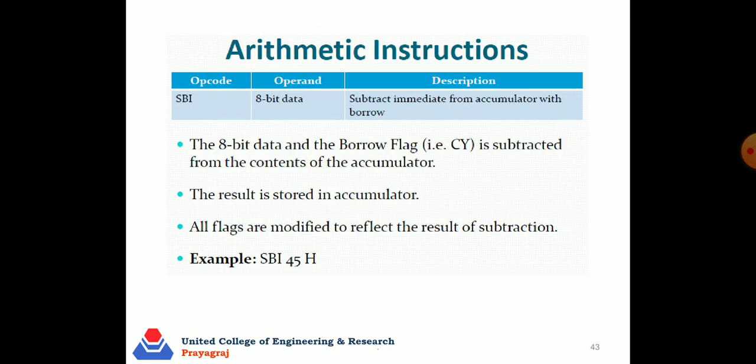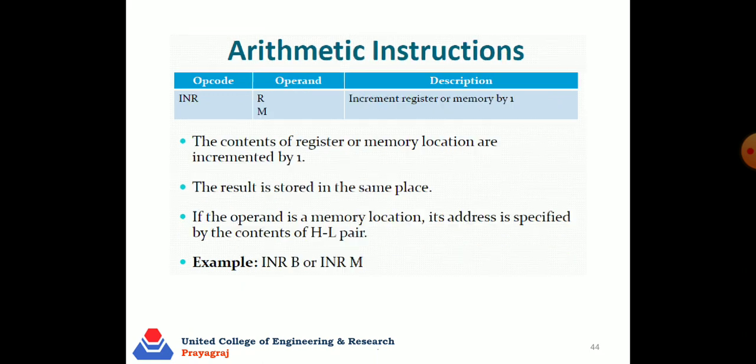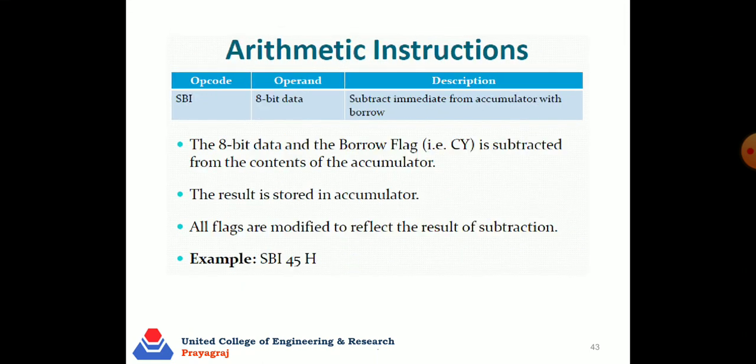SBI, it is not State Bank of India. It is subtract immediate from the accumulator with borrow. So the 8-bit data and the borrow flag, meaning the carry flag, are subtracted from the content of the accumulator, and as we know, the result is stored in the accumulator.